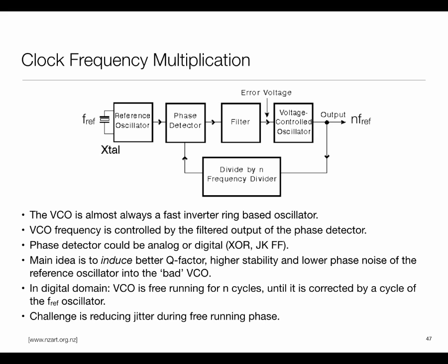So if their frequencies are matched and the clocks are toggling at the same time, then their edges should be perfectly aligned, and therefore any gap between their edges is an error. And if I can drive that error down to 0, then I am in good shape, because if I can make this signal identical to this, then this signal would automatically be n times that. So driving down the phase to 0 is also ensuring that the frequency here and here are aligned.